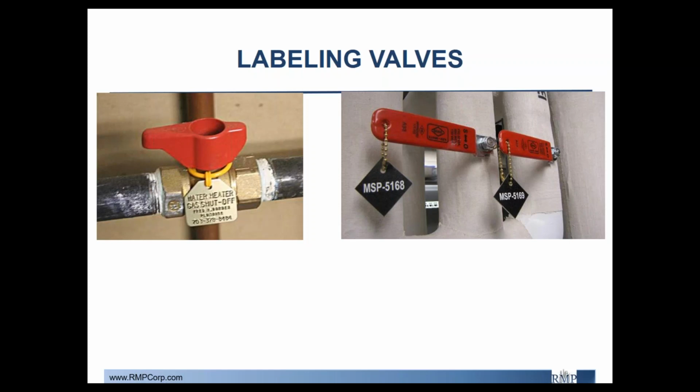And often when you're labeling valves, you have to keep in mind that if these are valves that are commonly opened or closed, it can wear away the labels and might tear off the dog tags. So proper upkeep is also very important, to make sure that you have some kind of a PM cycle on your labels to make sure that things are up to date.